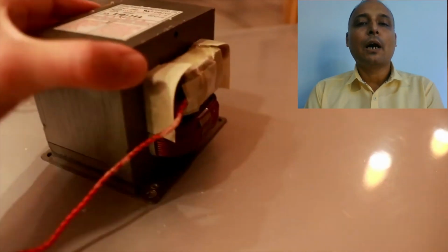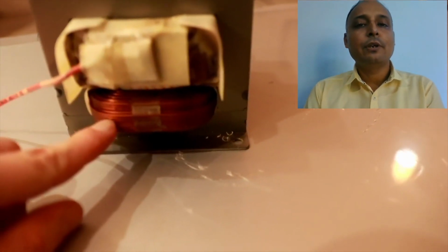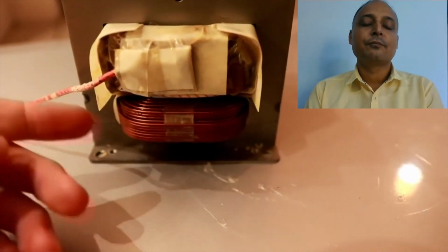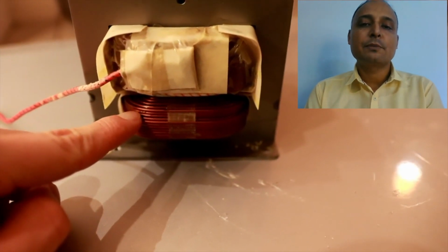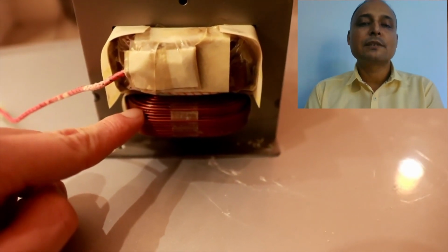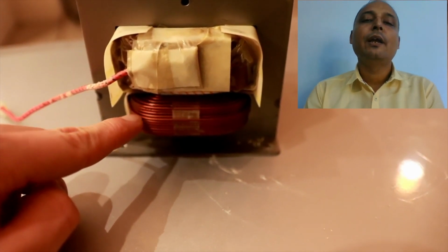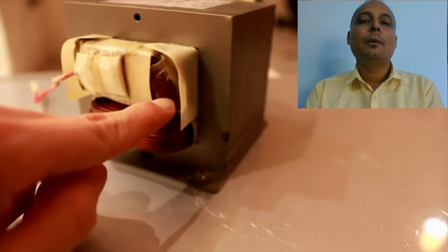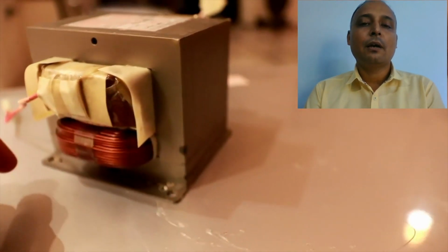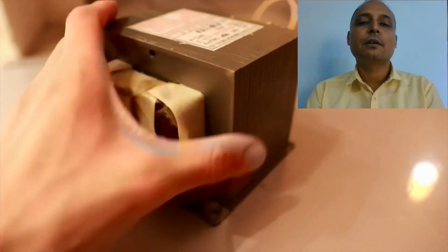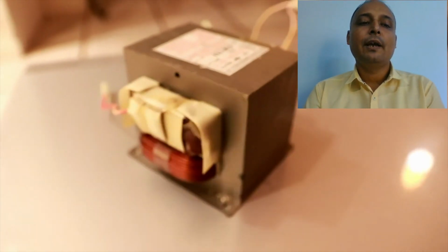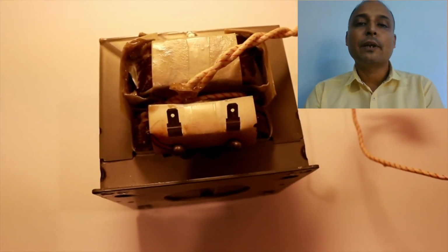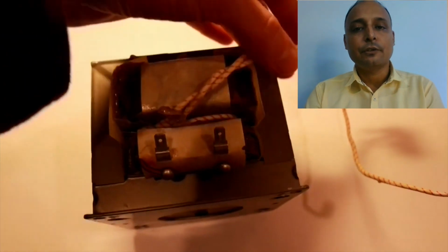Now this transformer output or outlet connection actually goes directly to the rest of the circuitry, mainly the magnetron circuit. And this transformer has now been rewound, that means the winding has been changed, and the changed winding is now connected to this connector so that power supply can be given to the microwave oven. Now here there are connections of the primary side. One is neutral, the other one is live, and this particular type of connector is connected to provide power supply to the rest of the microwave circuitry.